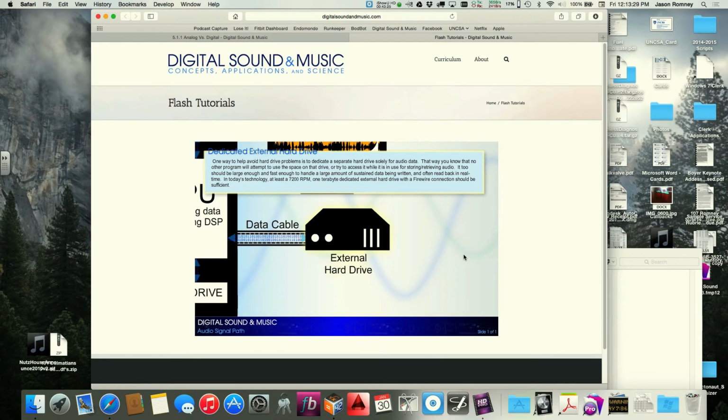Okay, and this used to be more problematic than it is today, but for a while there were a few different chipsets floating around for FireWire hard drives. There was the Oxford chipset, and there was another one called the Prolific chipset. And the Prolific chipset proved to be really horrible for sound because it was not particularly good at continuous, long-term streams of data. Like it was really good at delivering big amounts of data really fast, but it wasn't so good at keeping up with a steady stream for some reason. And the Oxford was, and is.